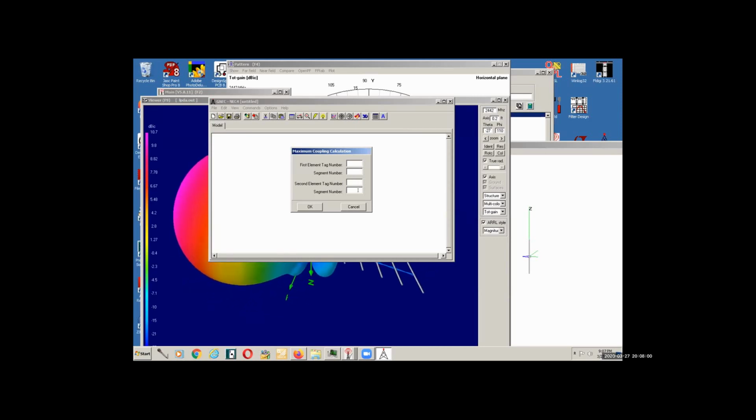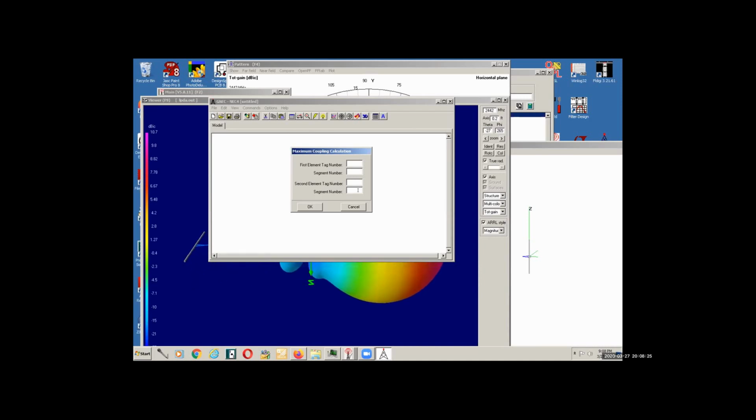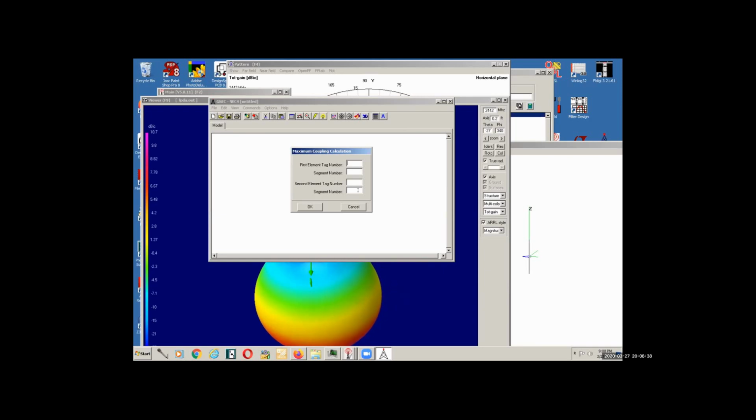Now, it'll do these couplings at the frequency you specify. So you have to specify the frequency, right? Okay, makes sense. Obviously. So whatever your transmit frequency is, you specify it, and then you see the power at that transmit frequency that would be received in all the other antennas. So if you have a 40-meter Moxon that we're transmitting with, and we want to see how much energy gets picked up in the 20-meter Yagi, yes, it will do that.